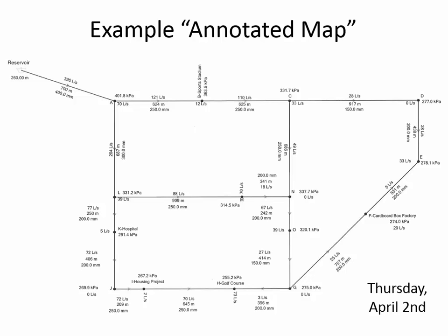So all of the external flows are labeled. Here's a demand. I think that if I'm remembering correctly, this junction feeds into the southern loop. This one feeds also into the southern loop. Now this was from a previous year when the students had to put pipes between all of the junctions. You have some further flexibility where, for example, maybe you could cut this pipe out because the water could come in from other directions. So yours doesn't necessarily have to look like this in terms of where the lines are, but what I'm talking about is there's some nice things as far as the annotations go.